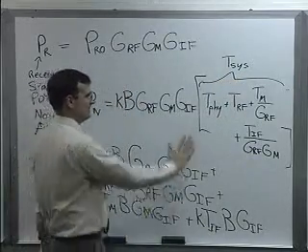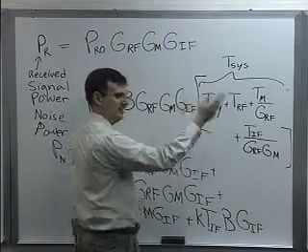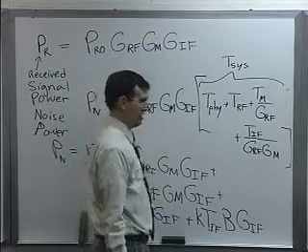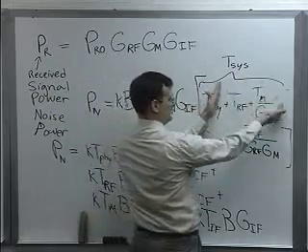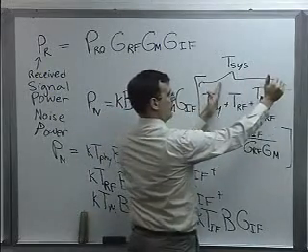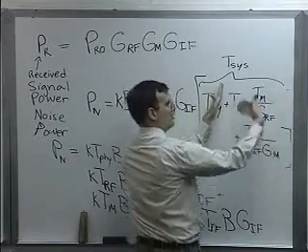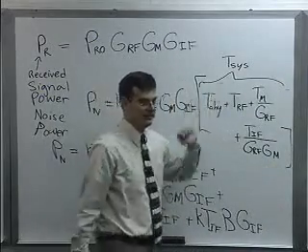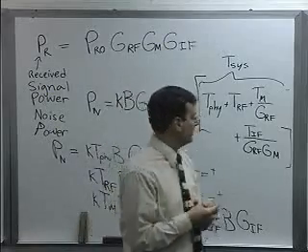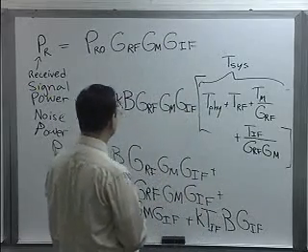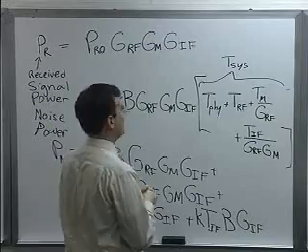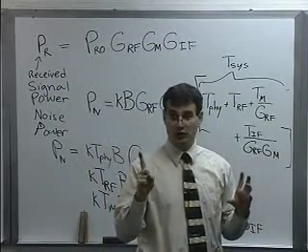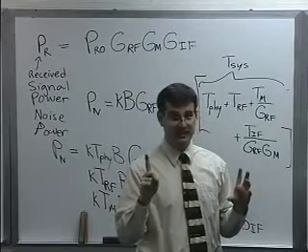And a lot of times the T_sys won't include the physical temperature because it doesn't make presumptions about where you're pointing your dish and where you're operating it. It might just include these terms here for basically how much noise your receiver adds into your signal. Brad, do you have a question? Yes. Is there a reason the first term doesn't include the gain from the antenna? That's right, because typically the question is, why does the first term not include the gain of the antenna?